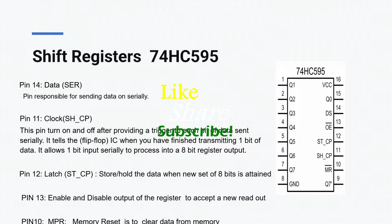The transfer of those 8-bit output is acknowledged by a storage pin or a latch pin. This pin is responsible to store or hold the data when a new set of 8-bit is attained. And then we have pin 13, which is the output enable pin of the register.